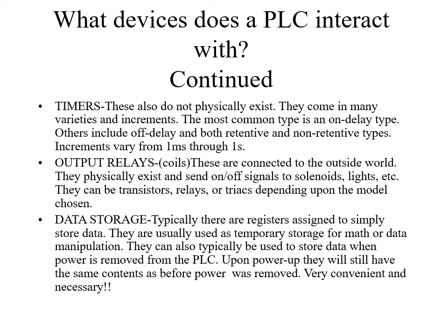Fourth, we have timers. Again, these also do not physically exist. They come in many varieties and increments. The most common type is an on-delay type. Others include off-delay and both retentive and non-retentive types. Increments may vary from 1 millisecond through 1 second. We can take a look at this later.